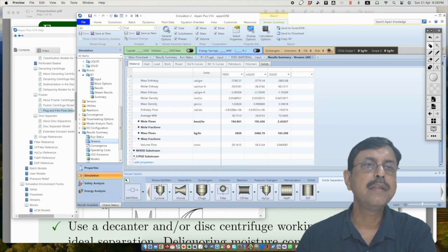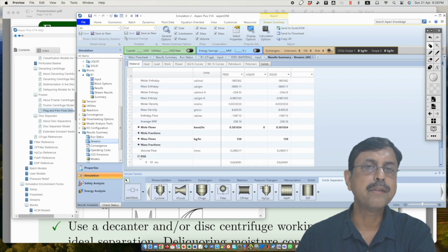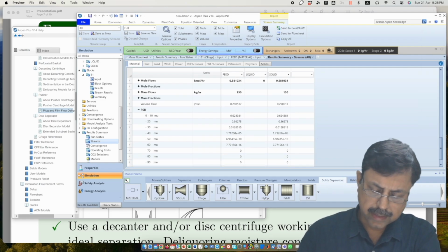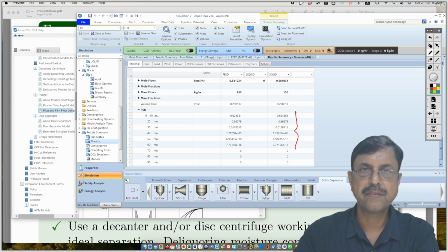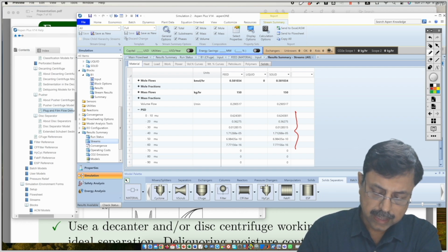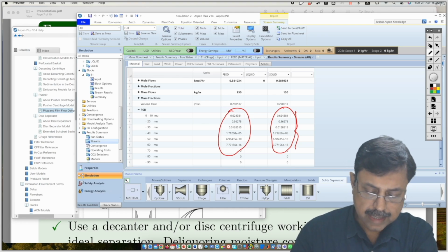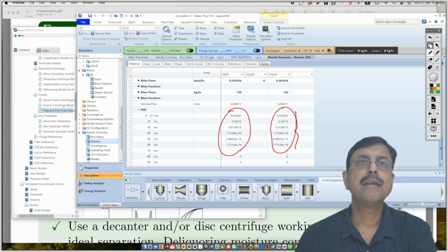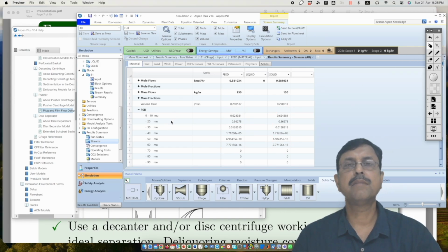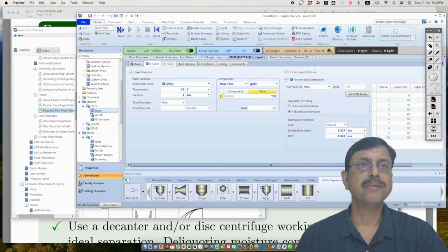And if you want to see the particle size distribution, you have to find PSD over here. It is understandable because we have only one solid outlet and all the solids have come through that outlet. So whatever the inlet particle size distribution, the outlet particle size distribution will be exactly the same. So there is no prize in guessing that. So that's how the simulation stands. And as I said, this may not be the best simulation because we have used some arbitrary random parameters. So it's okay.